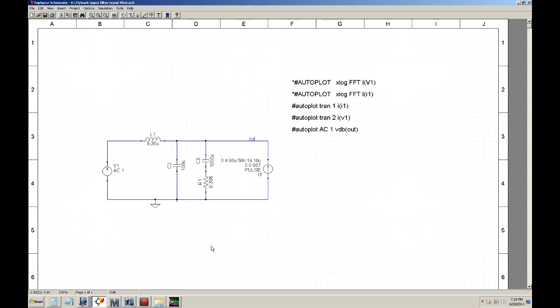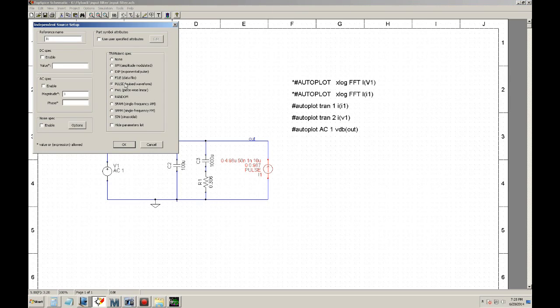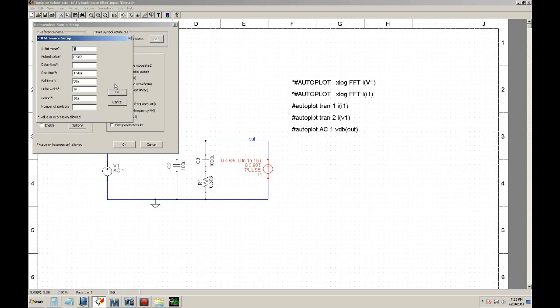So now what we're going to see is how it attenuates this current, the current that the flyback converter would be producing. And what you can do is, instead of using a flyback, the flyback can be modeled as a current source. And you try to duplicate basically your primary current.